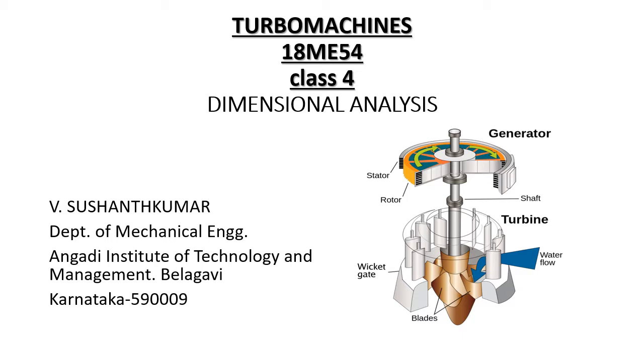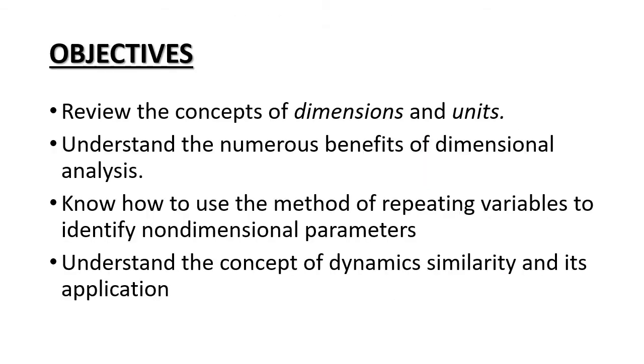In today's class we are going to discuss dimensional analysis. We will discuss what is the dimension and units, and understand the benefits of dimensional analysis, and how to use the Buckingham Pi theorem and method of repeating variables to get the non-dimensional parameters, and understand the dynamic similarity and its applications.